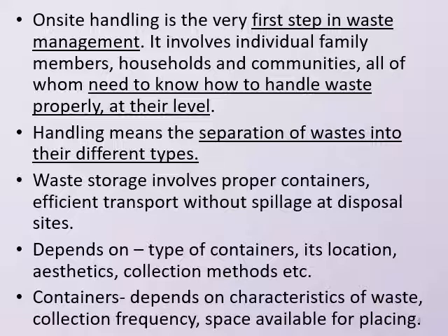And collection frequency: obviously the volume of container will depend on the collection frequency, whether the collection is done on a daily basis or weekly basis or once in 2 days or once in 3 days. According to this frequency, container volume or capacity of the container should be determined.